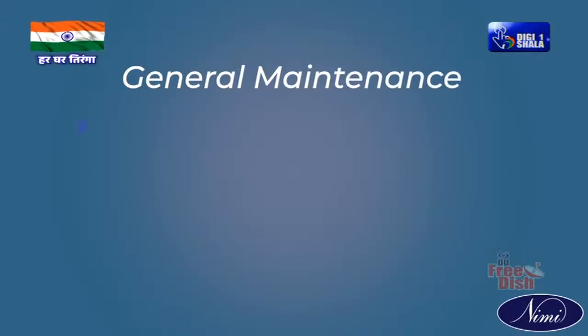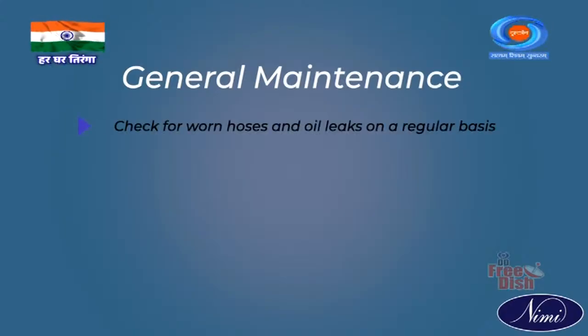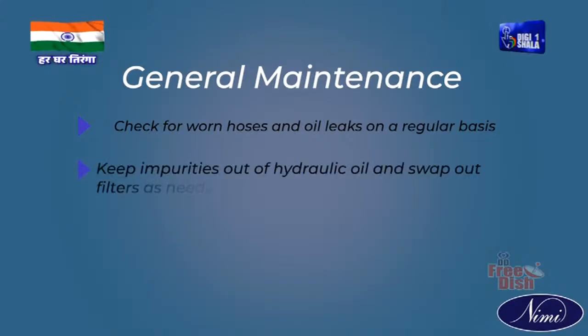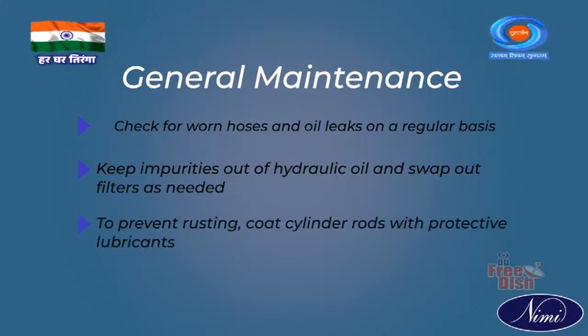General maintenance. Check for worn hoses and oil leaks on a regular basis. Keep impurities out of hydraulic oil and swap out filters as needed. To prevent rusting, coat cylinder rods with protective lubricants.